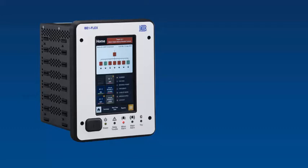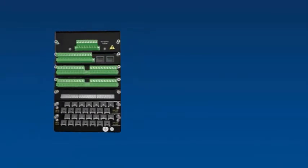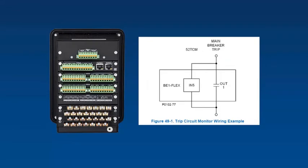With the high number of breaker control capability of the BE1-FLEX, it was important for us to design a method that allows you to scale the trip circuit monitors to as many outputs as necessary. The way we monitor this in the BE1-FLEX is by wiring a contact status input across the breaker trip output. This is just showing one example of output 1 that is going to be designed for the mains breaker trip, but you could repeat this process as many times as you wish because we can utilize as many inputs and outputs as we wish in the scenario. Next, I'll be jumping into BESTlogicPlus and we'll show you how to implement.